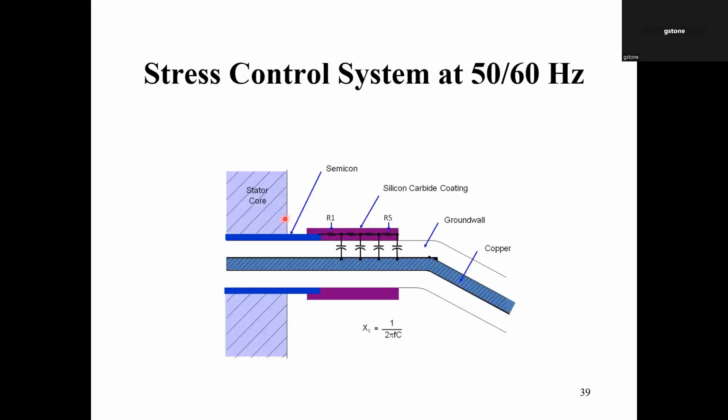Okay, so let me skip the words and go directly to a diagram. Here we're looking at this sketch from the rotor. Here is the stator core. This is a coil that's coming out of the stator slot. And this skinny little stuff here, which is actually quite fat usually, is the copper conductors. But I'm an insulation engineer, so I like focusing on the insulation. So the insulation is nice and thick here.